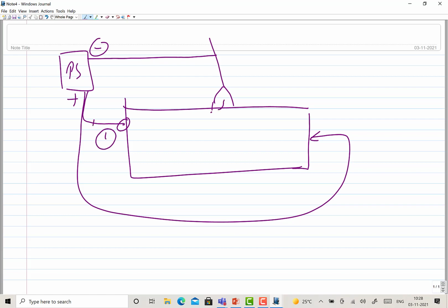So the flow of current will happen in this way, because current will try to follow the path of least resistance. When you have the connection at location 2, in that case the flow of current will be in this direction. So depending upon this connection of the power source with the base metal, that is known as the ground connection, the flow of current through the base metal is affected. It can help or it can resist the arc blow.